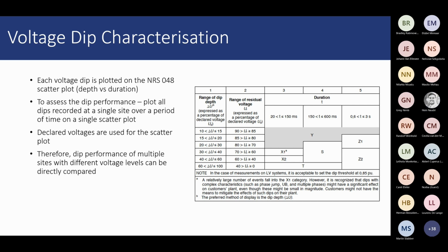With regards to Tiro's question on the relays, I'm not sure for the voltage dips, but we have set up Vector 2s, a couple of them, and used 3 relay outputs, if I'm not mistaken, 2, 3, and 4, for voltage regulation, unbalance, and THD. Our approach, when we usually test them, for voltage regulation, would be to set a limit of, say, plus minus 7% from the declared. So your compatibility upper limit would be 107.5%. And then we would set our limit at maybe say 107%.